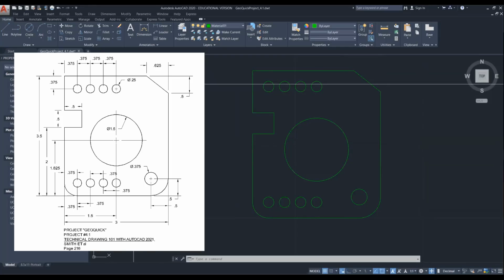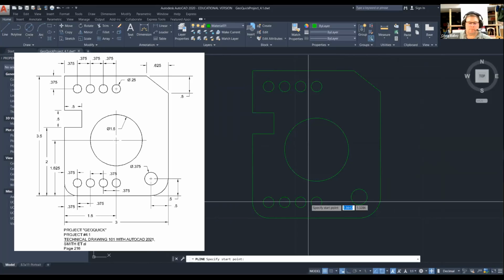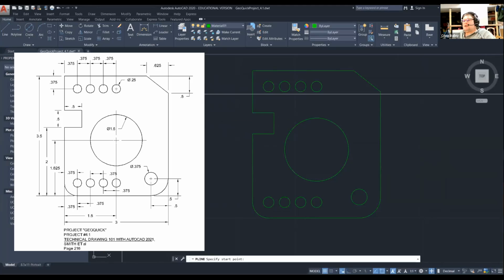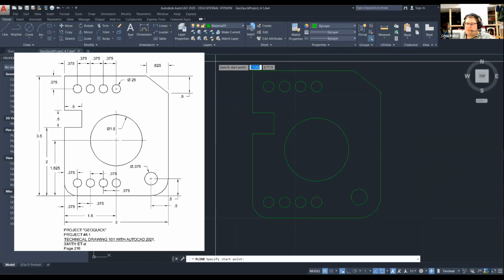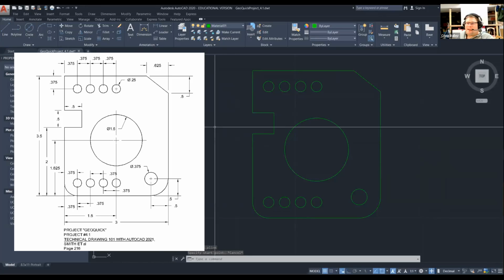Yeah, I was hoping you would say that because I don't. Do I just select polyline and then highlight everything, or nope. You're gonna actually convert them. You have to convert them to a polyline. So hit escape. Okay. And we're gonna start the P edit command, the polyline edit command. So just type it in. I don't know where the heck you could find it. I really don't.